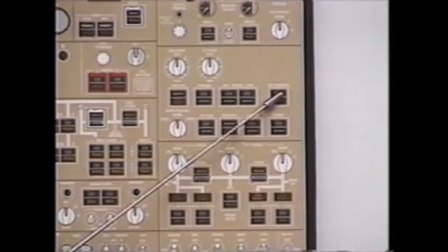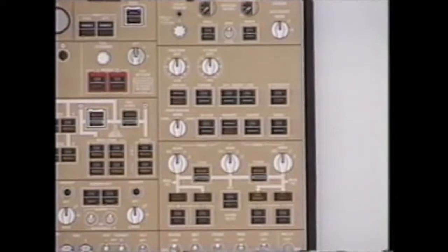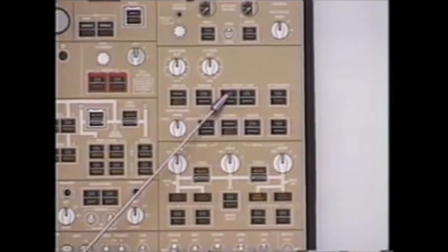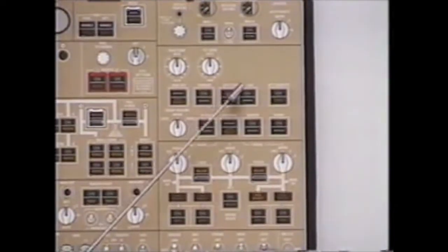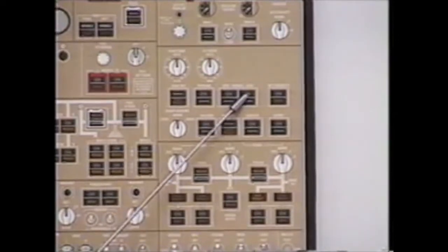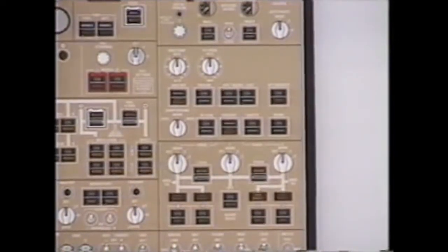Aft cargo heat uses hot pneumatic air from the center manifold to keep the aft cargo compartment at a desired temperature. Because of the aft cargo heat, all live animals will ride in the aft cargo compartment. The forward cargo compartment is heated electrically to about 40 degrees. Upper and lower recirc fans. The upper fans will always run as long as the switch is on. The lower fans will run when the packs are in normal flow, which should occur shortly after top of climb.